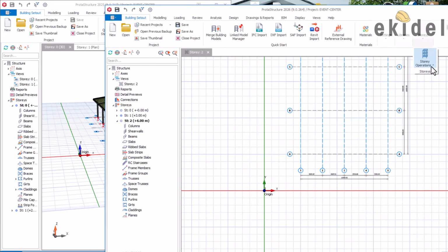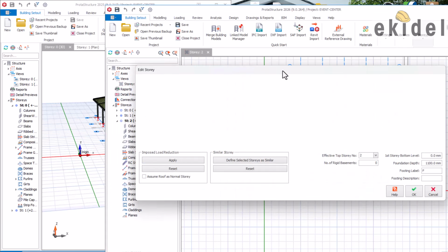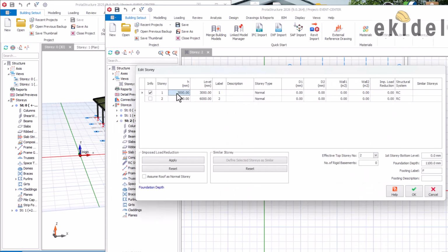We then come here now and change our height here, edit story, to change the story height. So we are going to edit the story now. For story 1, we are going to put in 600. I want to use 600 there because that is the pedestal height. Then on story 2, we use there 2.8. If you can put your eyes here, 2.8. So we've come here and type 800 for story 2, and then most importantly, this is very, very important.